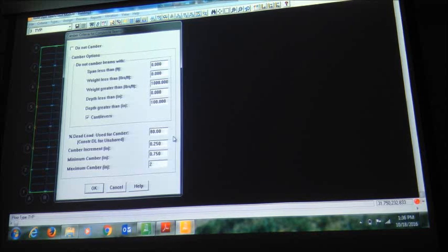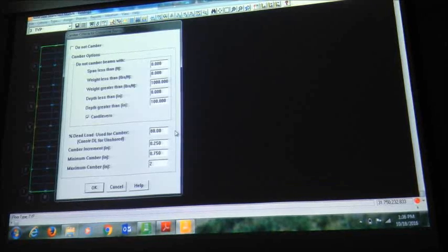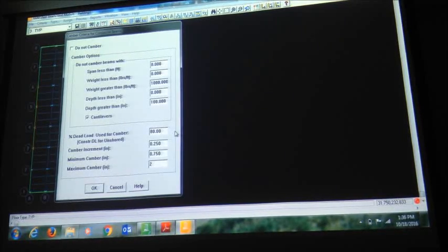Camber means steel beams are very elastic, right? So once you place them, they will kind of sag like that because of the self weight and the dead load. So what we do is we order the members curved like that, so once they are loaded, they become straight. That small portion is called cambering. Most of the gravity beams are like that.